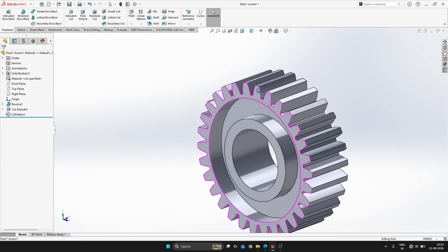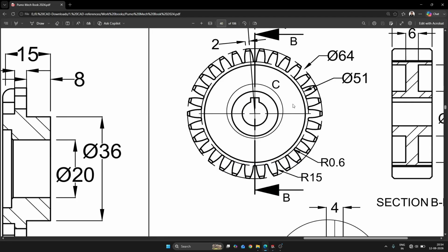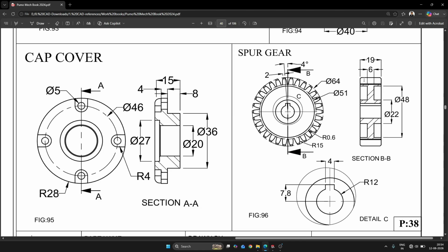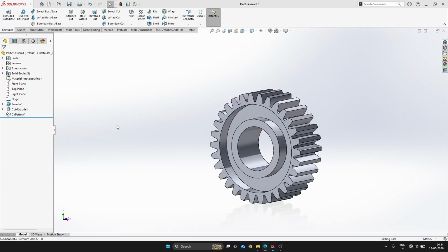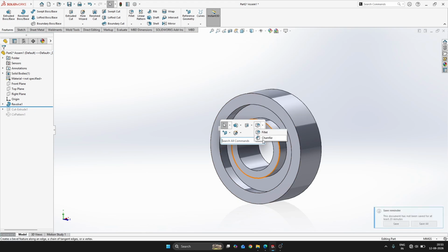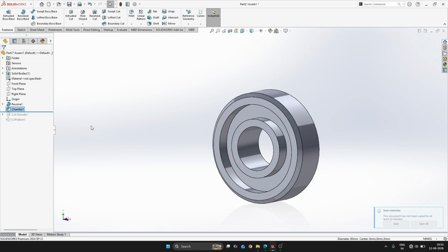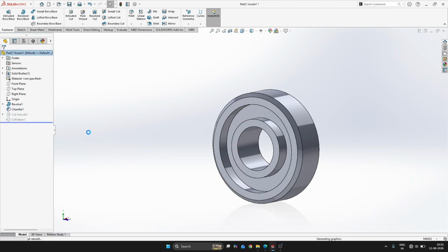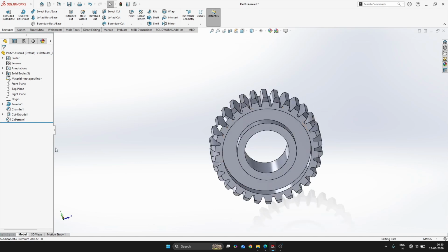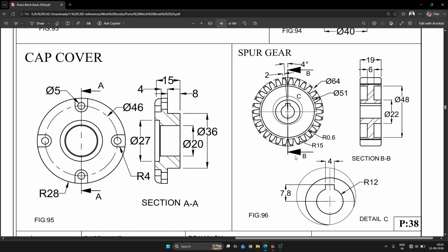Okay, so like this you have formed one spur gear, but you forgot one thing, which is you need to introduce this chamfer, and this keyway also. So you can see the scroll bar, right? Let's move it ahead of this cutout. Use the chamfer option and make two chamfers in opposite directions. Let's make the value 1. Now in this way you can restructure the tree. So now one thing we have not done yet is this keyway.